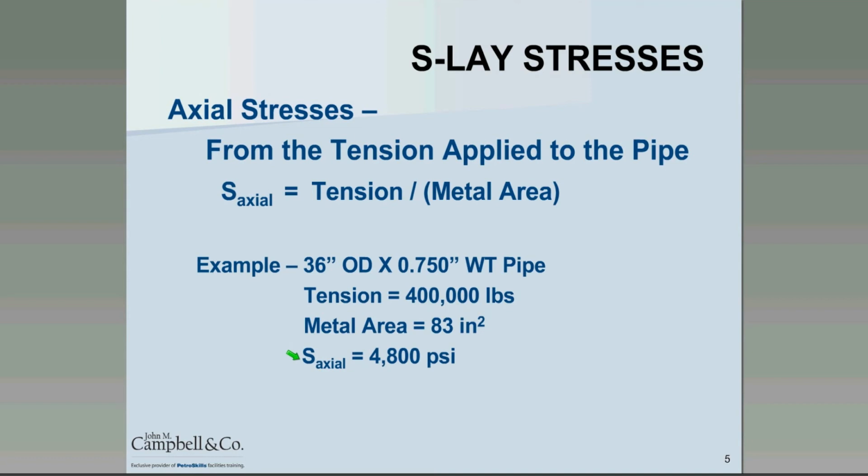If I'm looking at an X60 grade pipe, we're talking about a little under 8% of the overall yield strength of the pipe is being utilized to accommodate the actual stresses in the pipeline. Now, the diameter of the pipe can have a fairly significant impact.